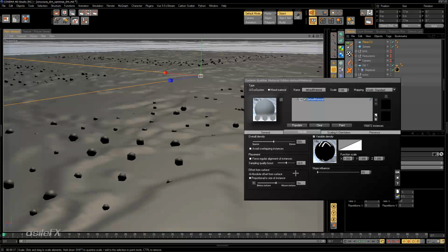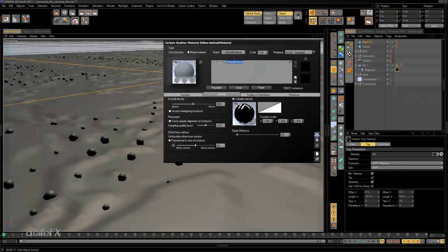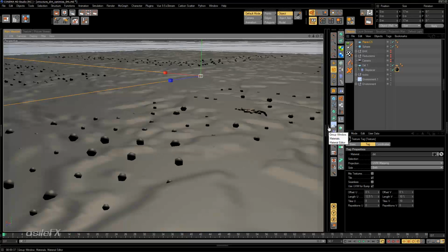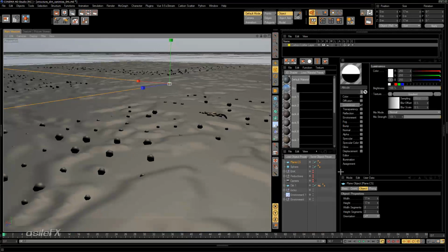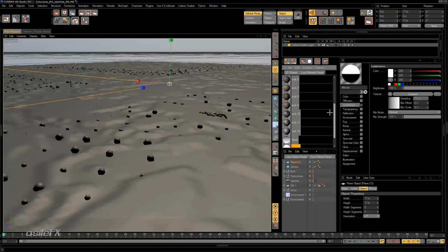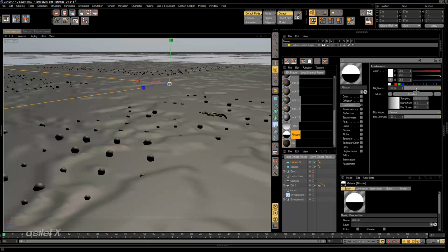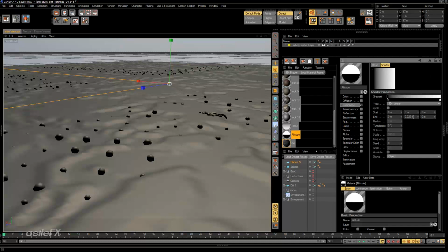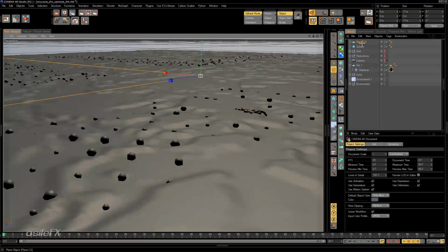So what we want to take a look at is the absolute offset from the surface. What we're going to need is that number that we used in the material, which I still have in the scene. So we can select the altitude, take a look at the gradient, and 0.022 meters. So we'll just type that in.